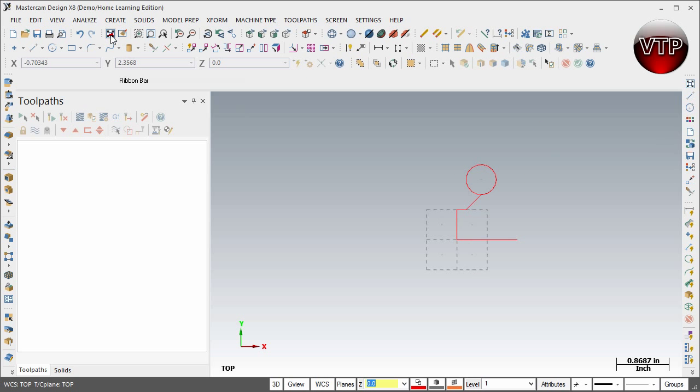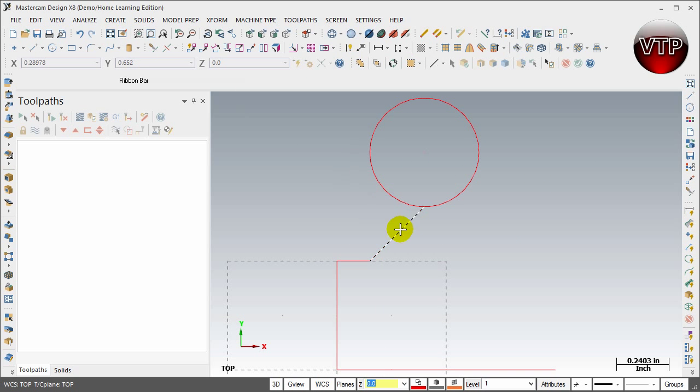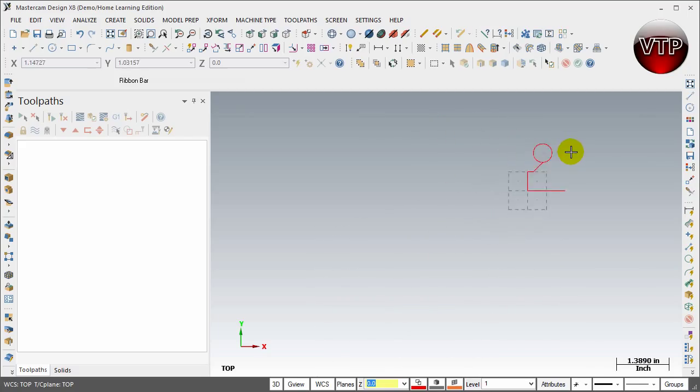I'm going to click on fit the screen. And then if you want to zoom out so you can see the screen a little bit better, zoom out. Then hold shift and press the up key to move it, and then press the right key to move it to the left. The only reason I'm doing this is because I'm going to place a point right now on the sketch to be able to connect this circle to the point. And let's learn how to do that.